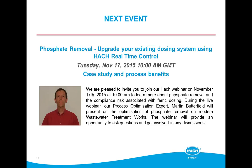So we've got options of high ranges or low ranges. If it's an unusual crude sewage, then we might use the AMTAC with, say, a 0 to 100 milligram per litre range. And for the final effluent, we typically use the low range AMTAC just to make sure we've got the greatest accuracy possible for the outlet reading. Okay, so I think that's clear, Stuart. So it's definitely an online analyzer. That's right.